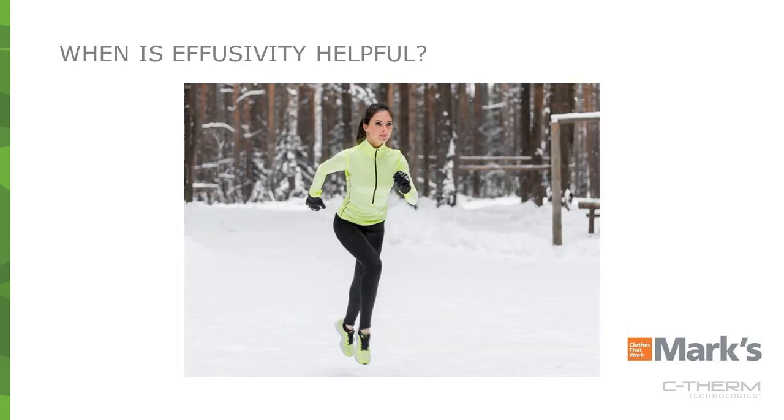Okay, so let's talk a little bit more about where effusivity is helpful, and we're going to pivot in more here to the case highlights. A major area of application is in activewear and textile, performance apparel, base layers, where we care about the coziness or the warm feel or the cool feel of the fabric, both in fabric selection and quality control, and looking at candidate materials for different seasons, and really giving us harder quantified data in terms of technical performance.